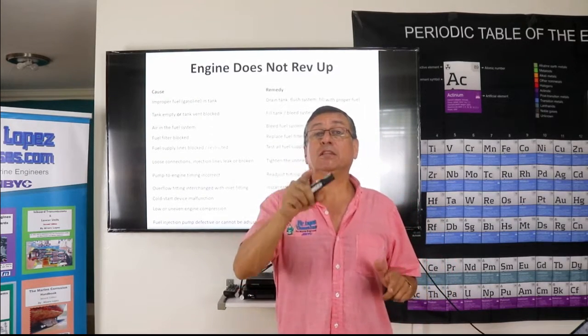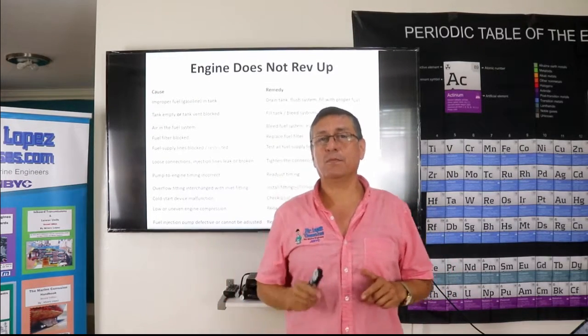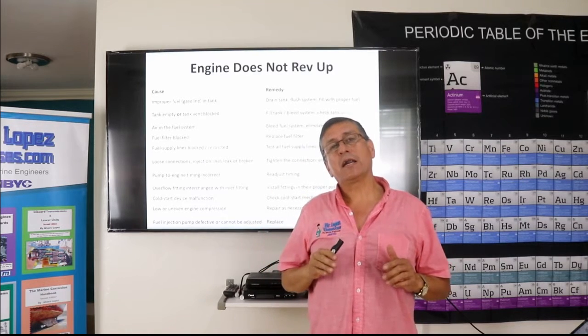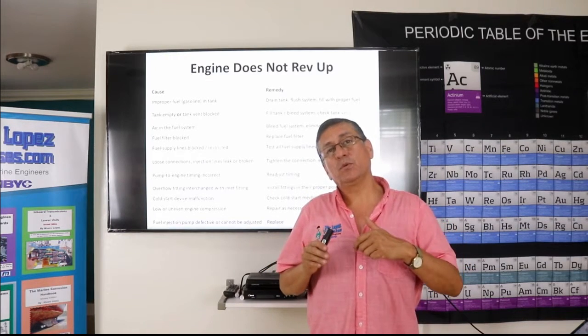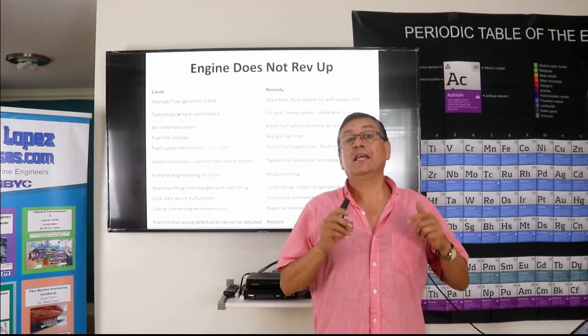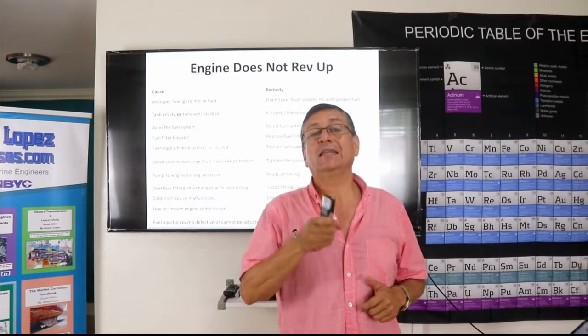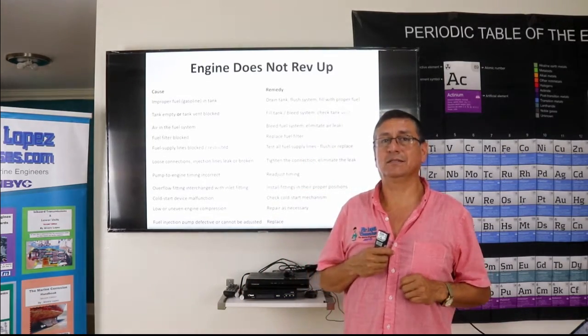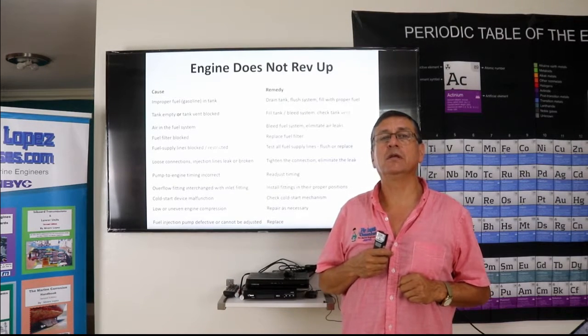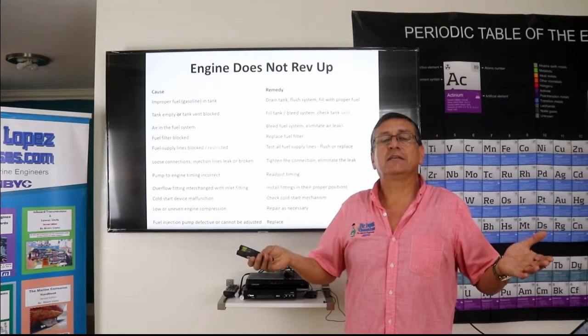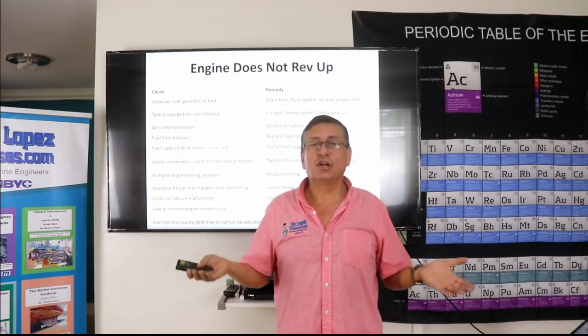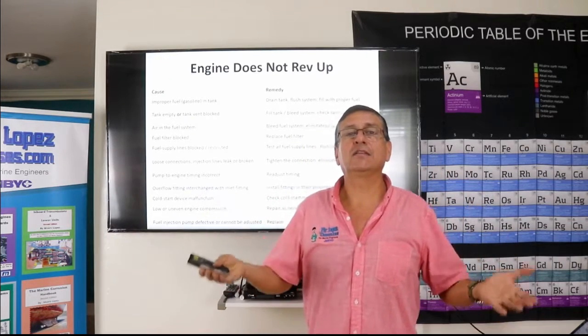What about the temperature in the exhaust manifold? Remember in the elbow where the water is mixed with the smoke? At that point you need to check the temperature in that elbow. It's critical. This is another important question. That's it, my friends. This is the procedure to solve problems related with fuel.